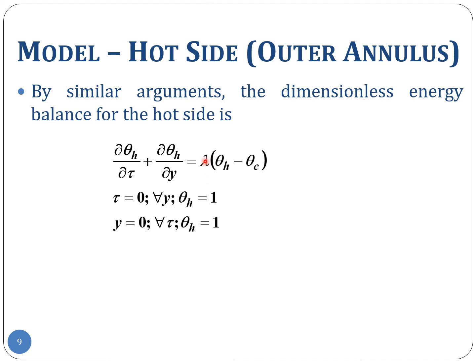So if the UAL term, the numerator term, dominates, then this temperature difference is going to play a major role, which means that there will be a significant change in the temperature of whether it is the hot fluid or the cold fluid, whichever you are looking at, along the length of the heat exchanger as well as with respect to time.